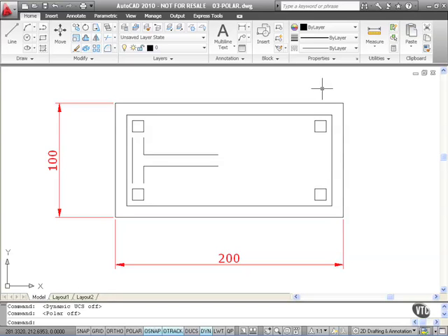Okay, so now we're going to look at polar tracking in AutoCAD 2010. Now when we looked at ortho previously, we realized that when we switched ortho on, polar turned off. The reason for that is you can also draw in an orthographic fashion using polar, providing your polar tracking angle is set to 90-degree increments, i.e. the lines are always at 90 degrees to each other, vertical and horizontal, or perpendicular to use the mathematical phrase.